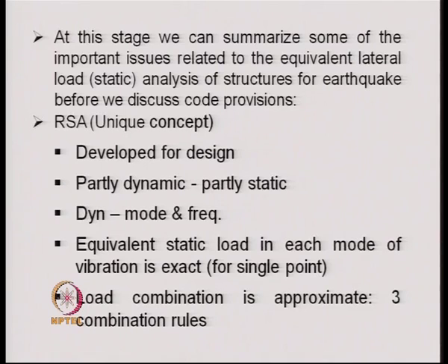And once we have the mode shapes and frequencies, the rest of the part is static. The equivalent static load obtained in each mode of vibration is exact for a single point excitation system, and it can be obtained from the fundamental equations of the multi-degree freedom system.